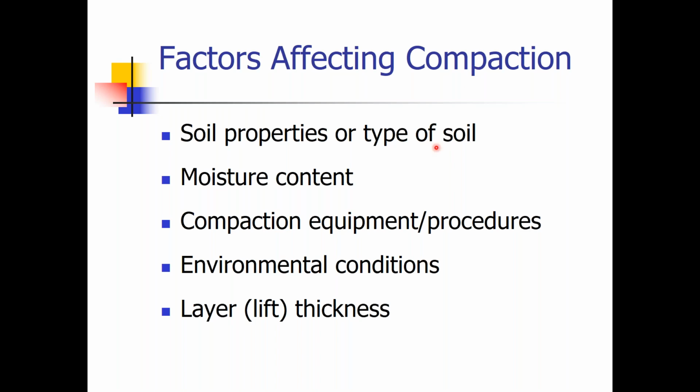Make a note if there are any weird environmental conditions around you. What if there's rain taking place? What if it's a rainy season? All of those things can affect your work. And finally, if you're putting down layers and lifts, the thicker you're putting those down, those can affect your compaction as well.